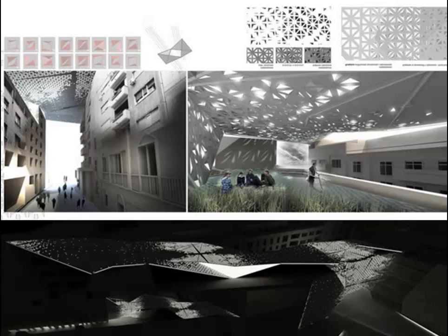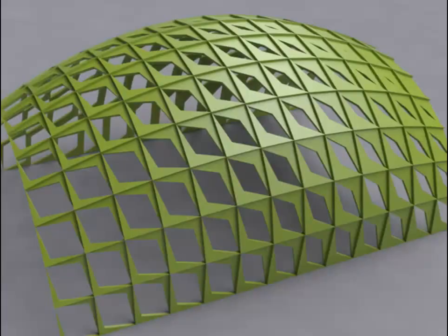And you could probably use your imagination and already begin to think about how you might do this parametrically in Grasshopper. This is essentially a surface, right? So you plug the surface in, get the points on the surface, and measure those points according to some attractors. I think in this case the attractors are located inside of these kinds of spaces. There's a little more to it than that, but you could already begin to imagine it.